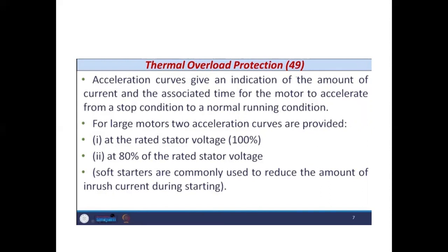But keep in mind that this is not a fault current. At the start, the current is 5 to 6 times the full load current. So this is not the fault current, and whatever device you use, it should be capable of discriminating between these two phenomena.